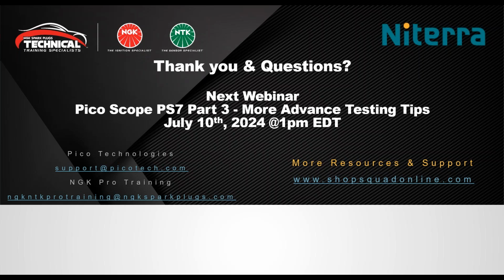I'll be honest with you, I use the TA388 for a lot of parasitic draws because it'll go around any battery cable of any car I'm working on. It'll get me down to an amp really easy, even under an amp, to be technical about it. And then if I have to switch to something lower, this would be the next one. This would be the next logical choice. It's actually something we designed and built for a VM, and we'll release it to the public.